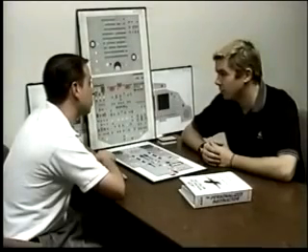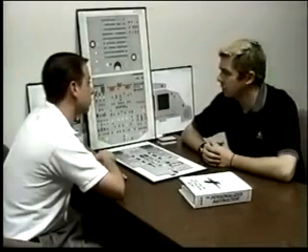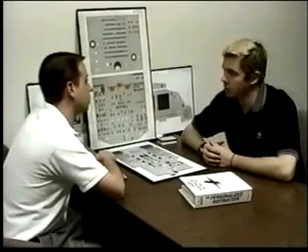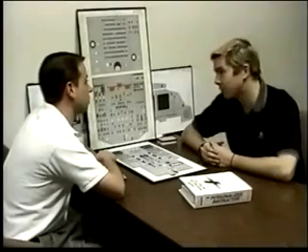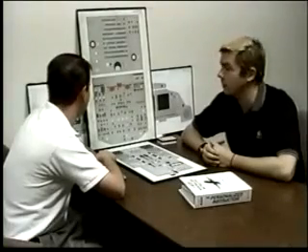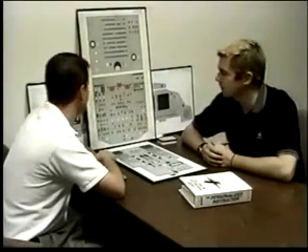If I didn't get the test to work, I'd first check the park and brake because maintenance might have chocked the wheels, and then release the park and brake. So before I called them, I'd look down to see if the parking brake was set. If that didn't work, I'd check the circuit breaker. If that still didn't work, I'd call maintenance.